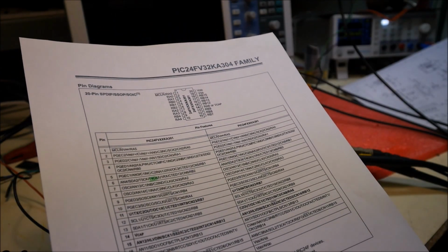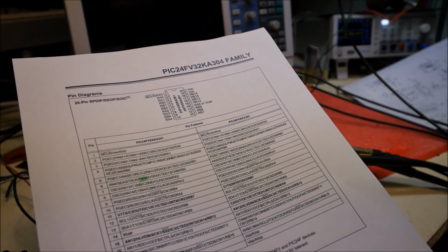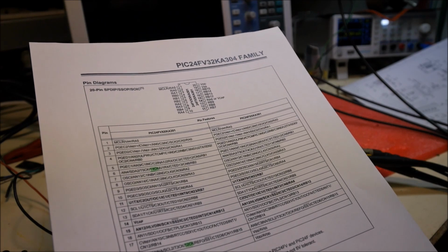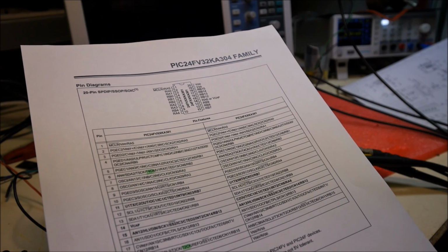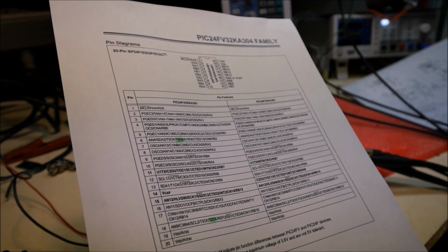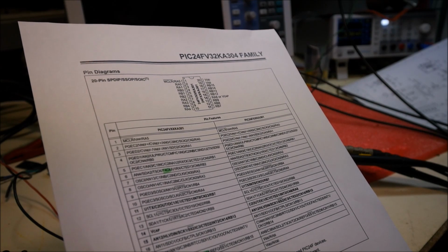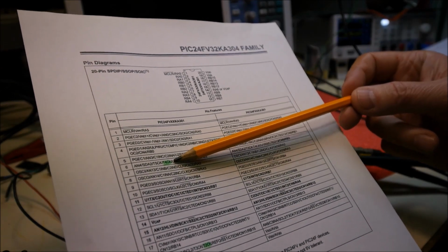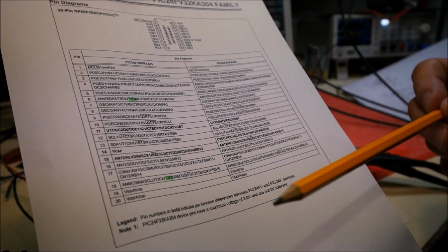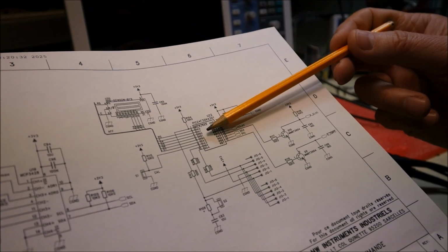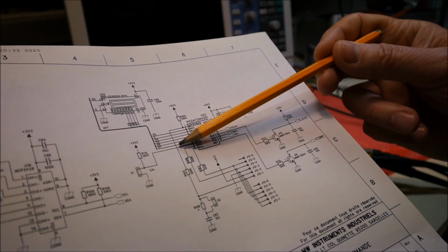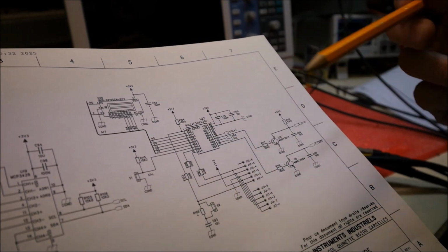What we need is actually two counters. One output gives pulses when the input voltage is positive. The second output generates pulses when the input voltage is negative. So I will use the two counters and subtract their values. I will use two 32 bit counters. One input is pin 6 here, T4CK. The second one is T2CK here. Unfortunately, pin 6 is used for the LCD display, so I will need to select another pin for this one, so we need to cut this line here.